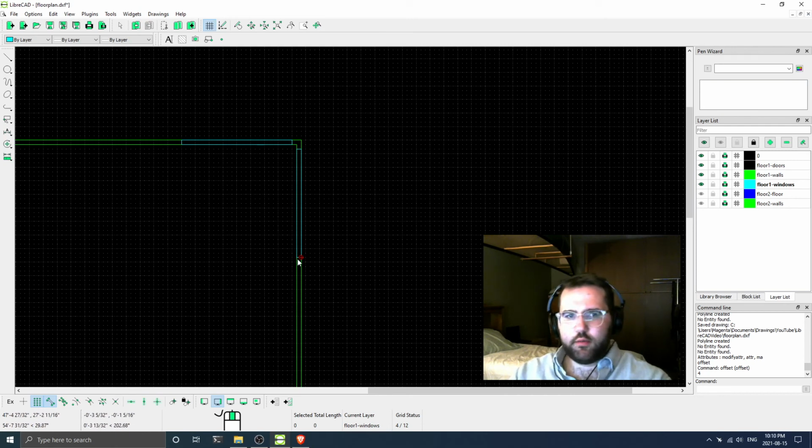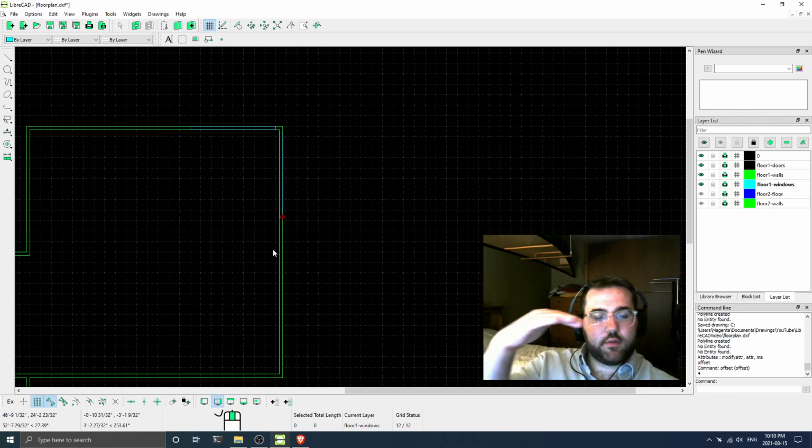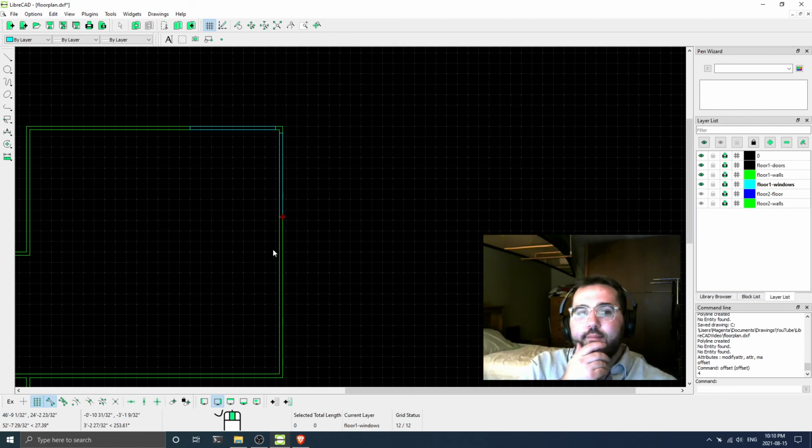Depending on what your intended goal is in terms of outputting this drawing, you would either want to move that line segment there, or you could just ignore it, because you would have that wall existing there just below the elevation of the window. So depending on your methodology or intended output, like if you're going to import this into Blender next, you probably would want to keep this as a continuous line segment underneath.